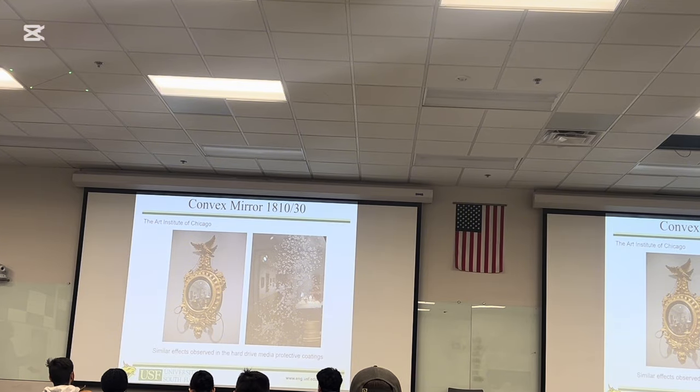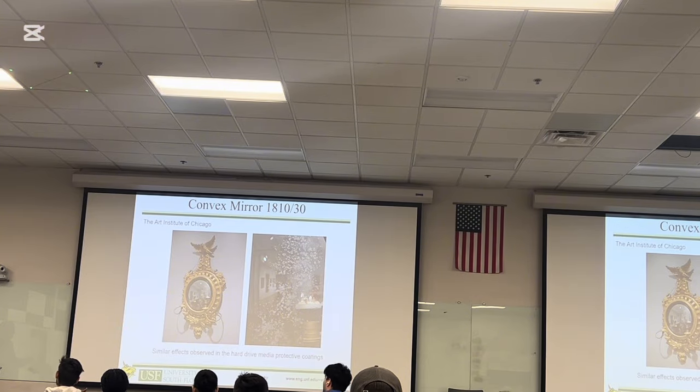Deterioration of a mirror. If you go to the bathroom, pretty much any bathroom at USF, you're going to see that the bottom of the mirror is delaminated. Okay? You don't see the delamination on the sides. You don't see it on the top. So this is a combination of a thin film in the back of the mirror that provides you the reflection, and the fact that people, when they wash their hands, sprinkle water, and water reduces the adhesion.